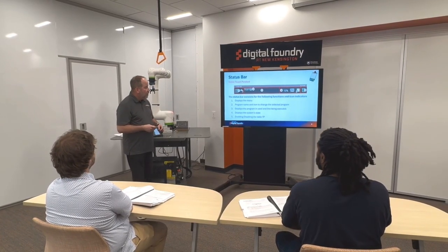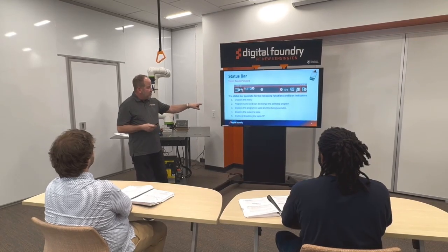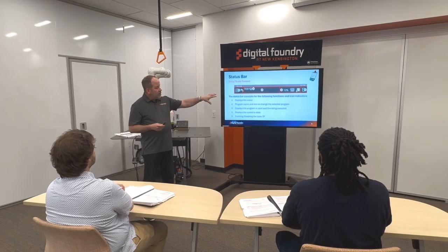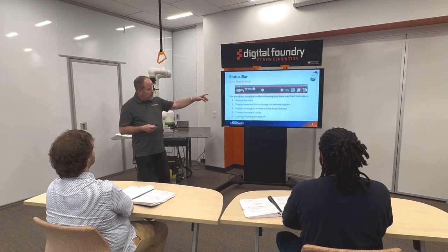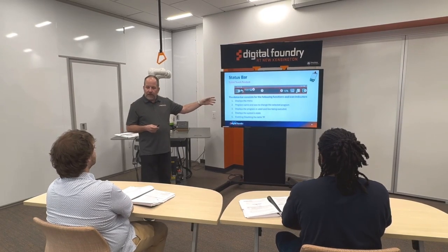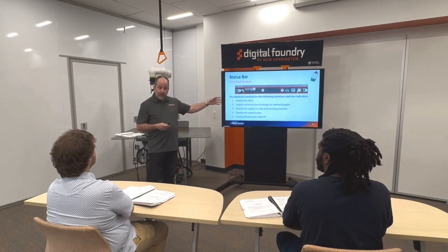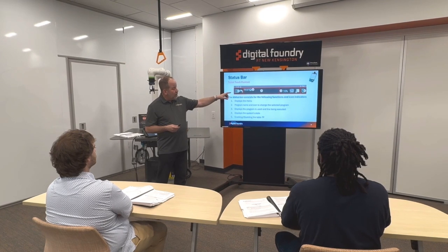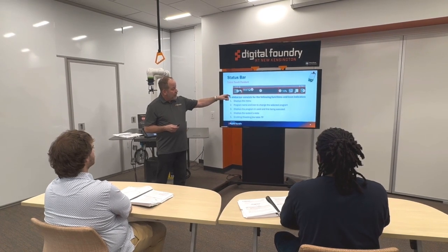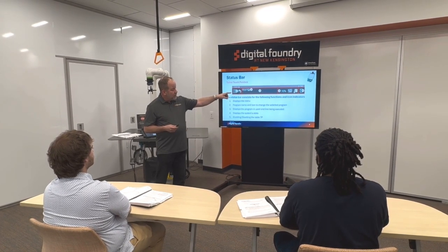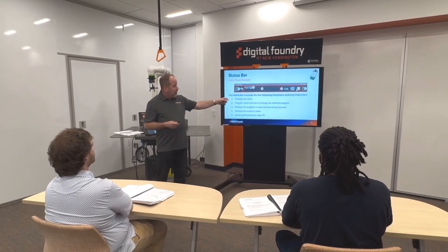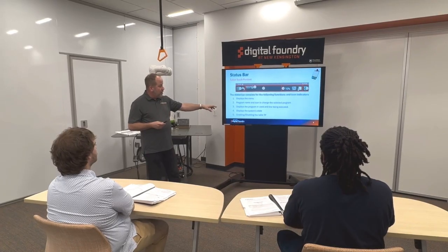Okay. 4 is the system display, and it displays the system state, and that includes things like the speed. So for instance, 10% means that you're operating at 10% of the maximum speed. And then next to that, it kind of infers that you're in auto mode, followed by that the robot is in the position to be able to program it. And last but not least, enabling, disabling the tablet TP.